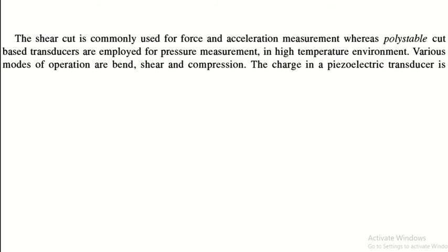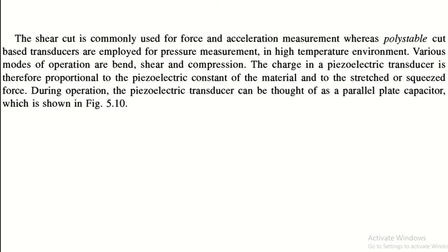Various modes of operation are bend, shear, and compression. When the force is applied, it is in the bending direction or shear direction or compression direction. The charge in a piezoelectric transducer is therefore proportional to the piezoelectric constant of the material and to the stretched or squeezed force.